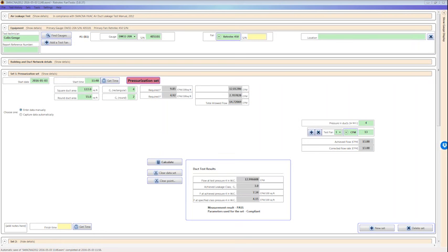Plus, even though the air is still circulating within the building, that blower may be running at 25% higher speed just to keep sufficient airflow, which is an energy penalty and tends to wear out the equipment. So the cost of duct testing for the life of the building is peanuts compared to the cost of not doing it, really.